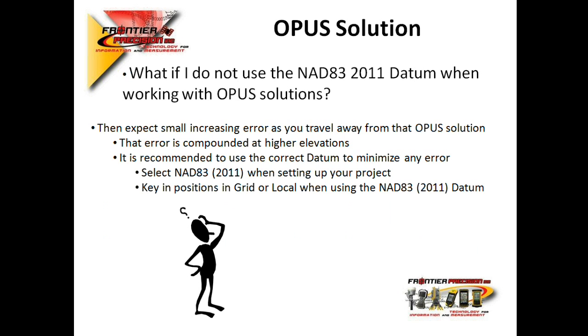So this is a question we get all the time. Well, what if I'm not using NAD83 2011 when I'm working with OPUS? You know, a project requires something different. Then you are going to expect some small errors as you travel away from your OPUS solution.